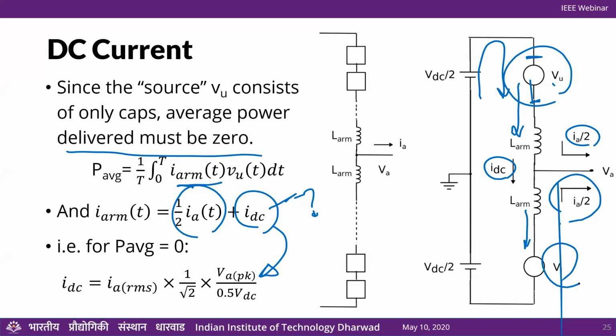So this should answer one of the questions that one of the attendees had, that was, do the capacitors carry fundamental current? And obviously you can see that each arm does carry fundamental current, and it cannot have zero power at any time period less than the fundamental cycle, right? So it charges in the positive half cycle, discharges in the negative, and so on.